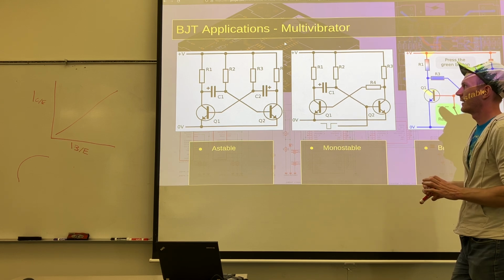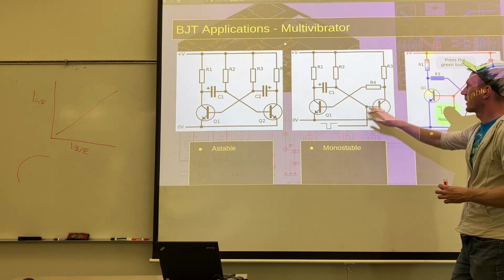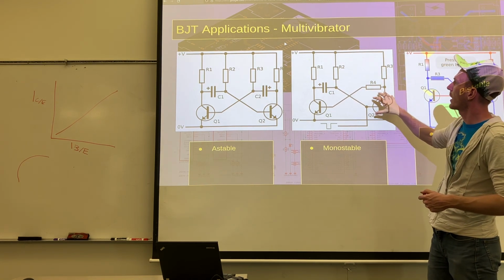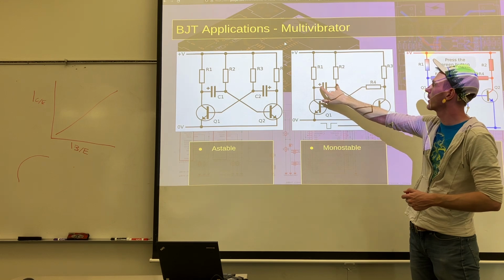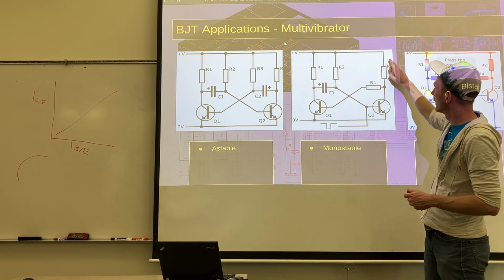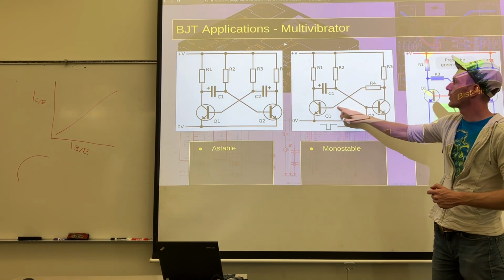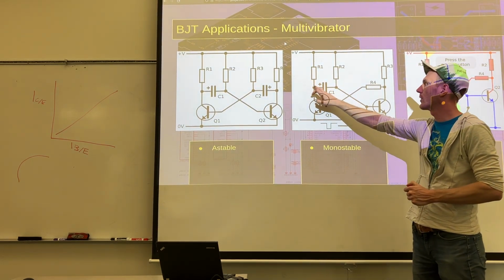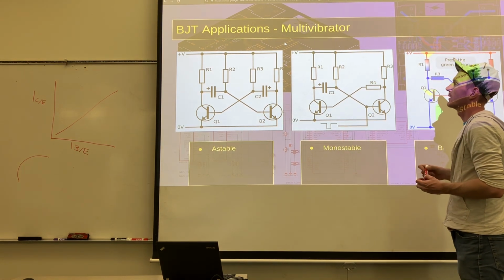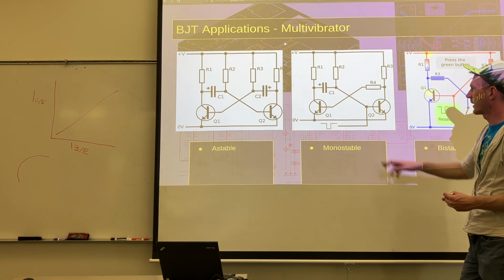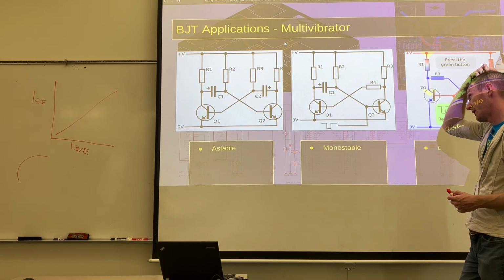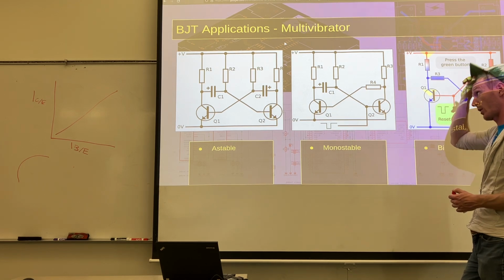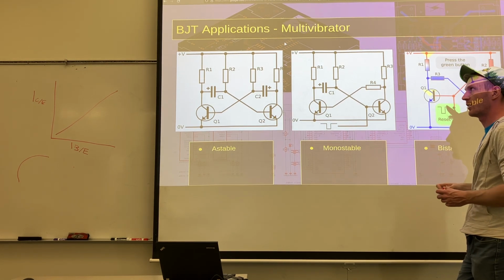So basically when it swaps states, you short this to ground, this stops, you're now dropping nothing across this, so your potential is now here, this gates, and this will start to discharge. And once this turns off, there's only a certain amount of time before this turns back on, which is dependent on your capacitor discharging.